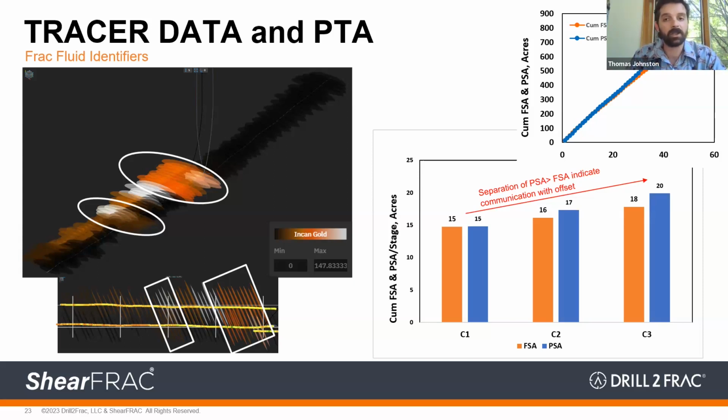And you can see in some of these child wells, we start to get that diversion. And so we start to see that we're perhaps potentially overstimulating those child wells a little bit. We're pumping a lot of fluid in, and some of that fluid is getting lost into a depleted fracture network nearby, and we're interacting with those offset wells. So bringing all these data sets together brings us some real confidence that we're creating the right amount of fluid loading and the right amount of proppant loading.